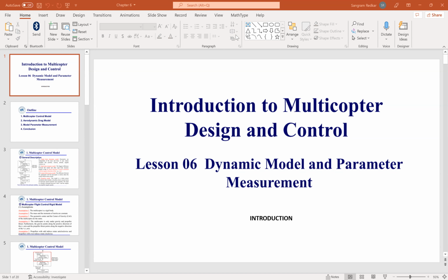What would change is inertia properties, control surfaces, and basically what we call control authority. So please understand, this topic is super duper important. I would actually go through the basic quadcopter analysis that is discussed in the textbook. That should give you some understanding for the aerial robotics class that you are doing. But the basic equations are the same for all aerial vehicles. For all UAVs, the basic equations are the same and they come from Newton's laws.